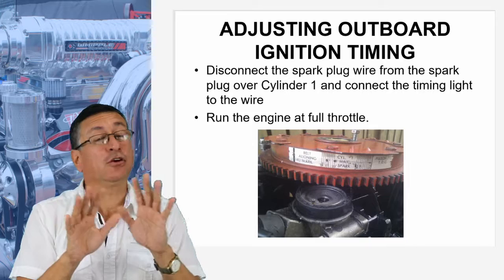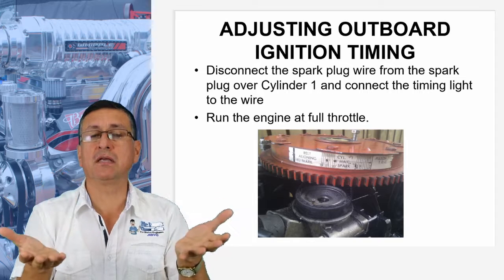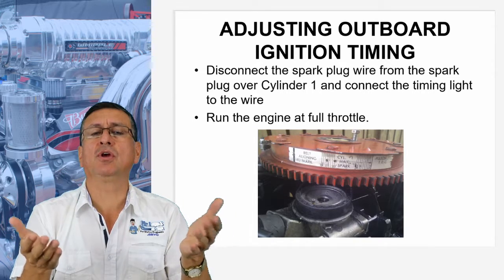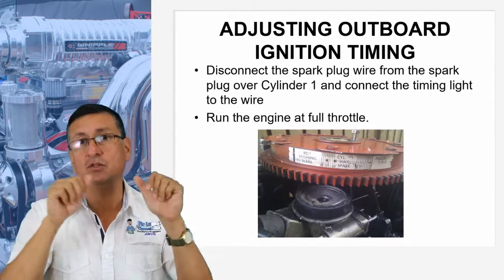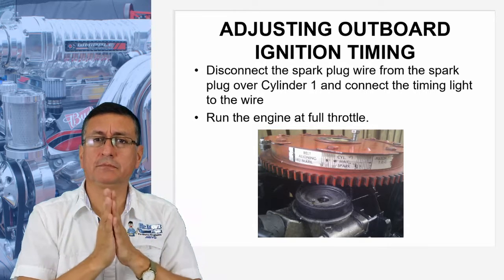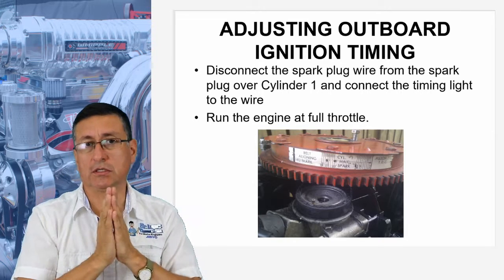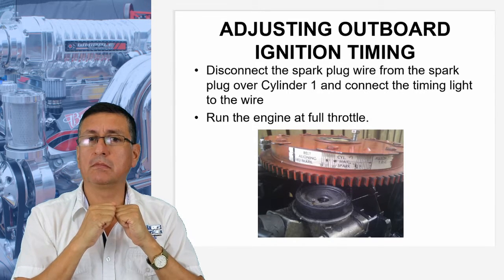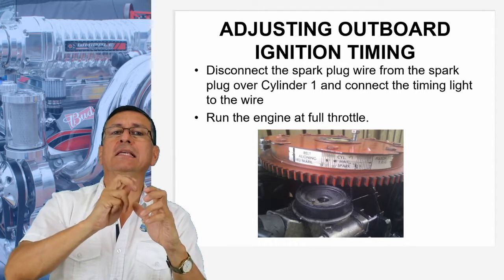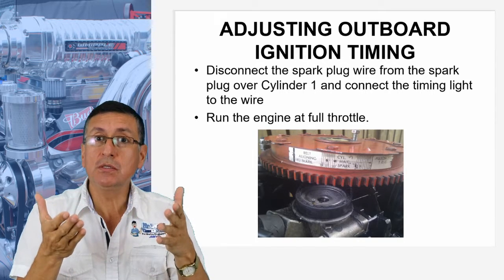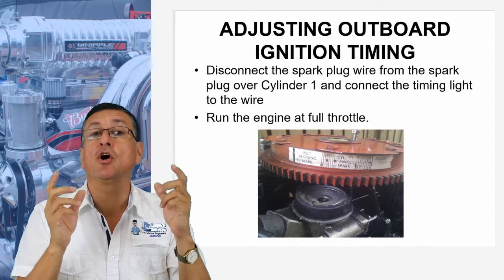The majority of the engines today adjust the timing according with the RPMs and the load automatically in the computer. You don't need to calibrate that situation. In outboards, it's the same. It doesn't matter if the engine is 2-stroke or 4-stroke. The computer calibrates the timing and advances or retards it depending on the load and the RPMs, according with information coming from sensors,